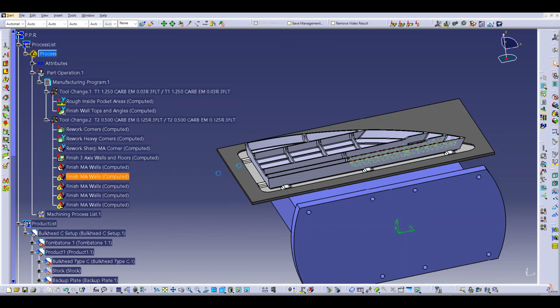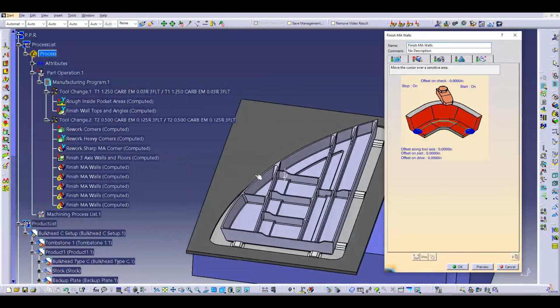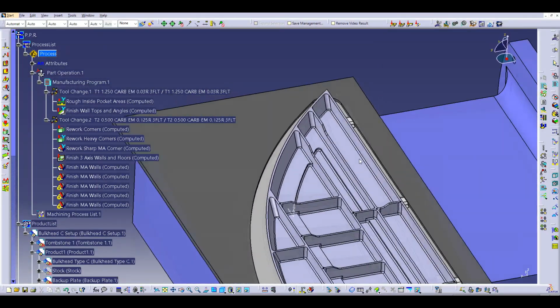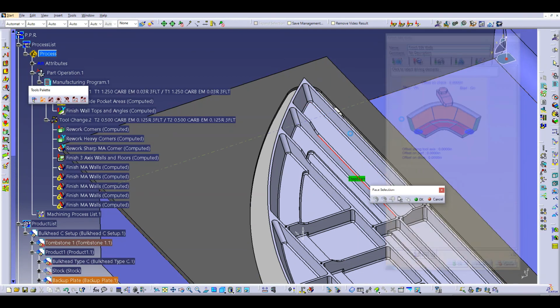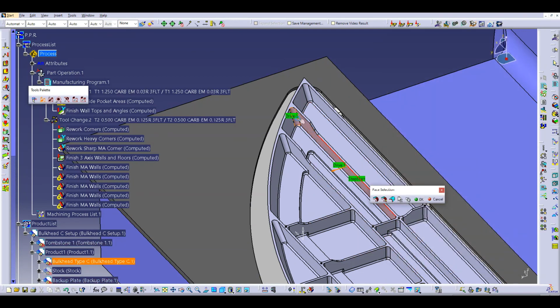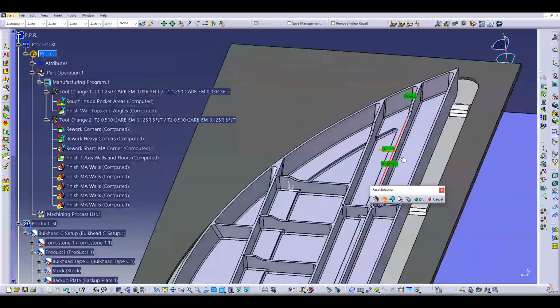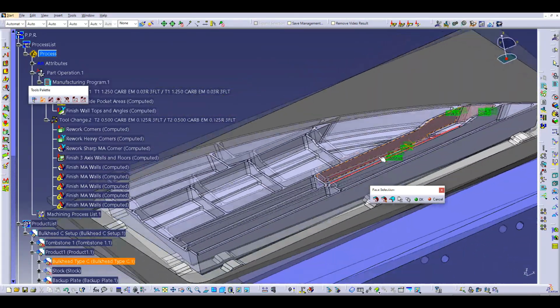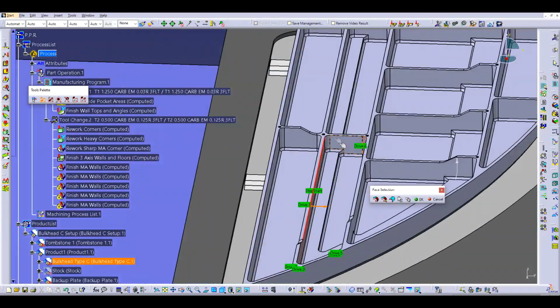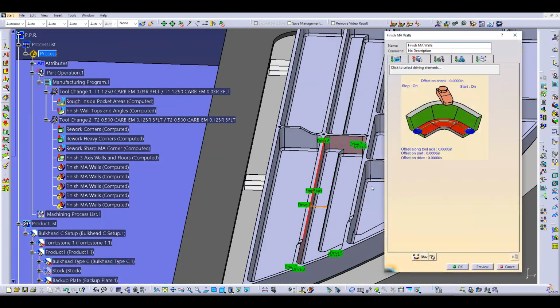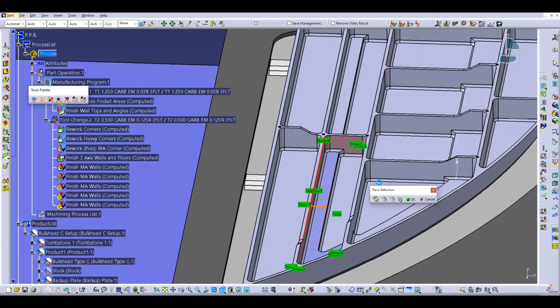And so we'll open up and we'll just assign the geometry to them. We're going to do it the same way we did the first one. I'm just going to grab those as a start and stop. This time I'll show you one of the navigations. I can say navigate until a face, and it selects all the faces in between up to that one. Then I can select the other ones, and we'll select our bottom, replay it.